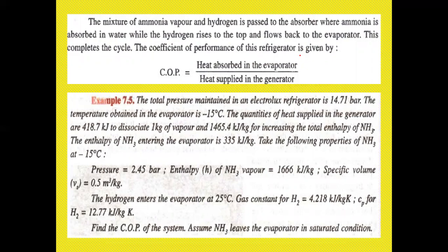If you see the coefficient of performance of this refrigerator, COP is equal to the heat absorbed in the evaporator divided by the heat supplied in the generator. So the COP of this refrigerator is the heat absorbed in the evaporator over the heat received from the generator.